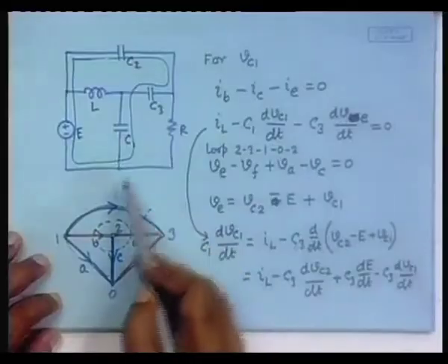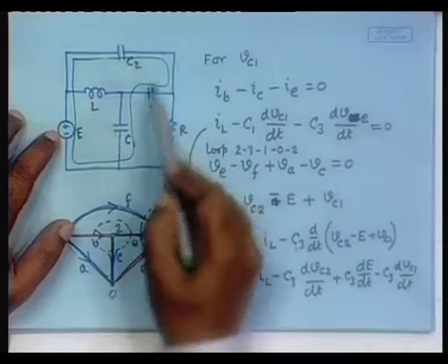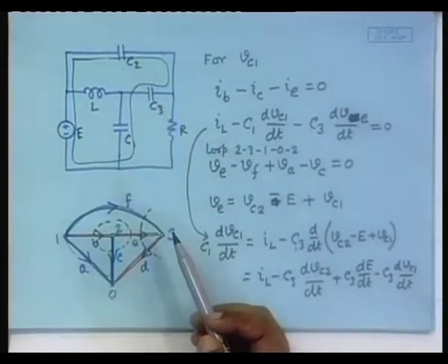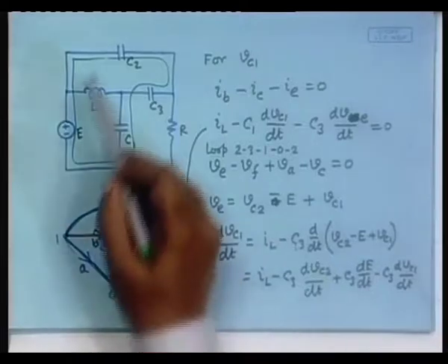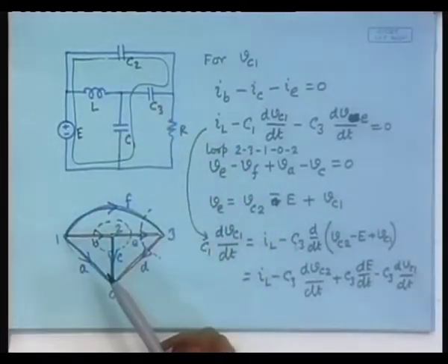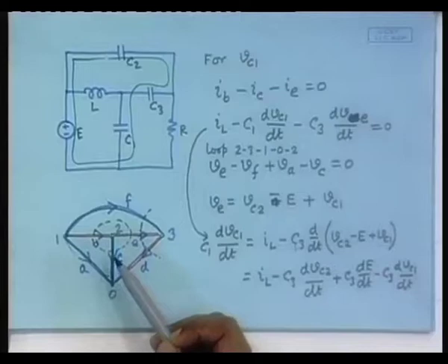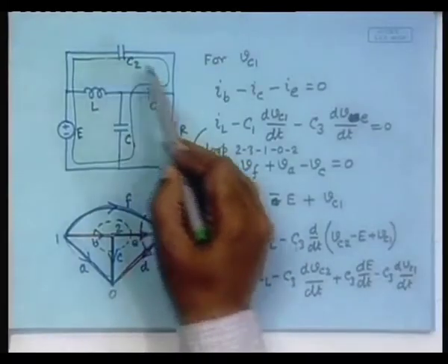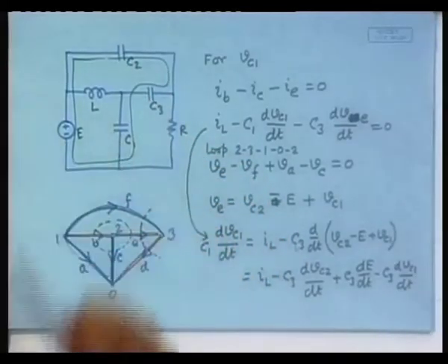If you connect it really like that, then these elements will experience enormous stress. Large currents will flow through the capacitances, and that is why this gives us the education that we should never connect a circuit so that anywhere in the circuit you can identify a loop that contains only capacitances and voltage sources.